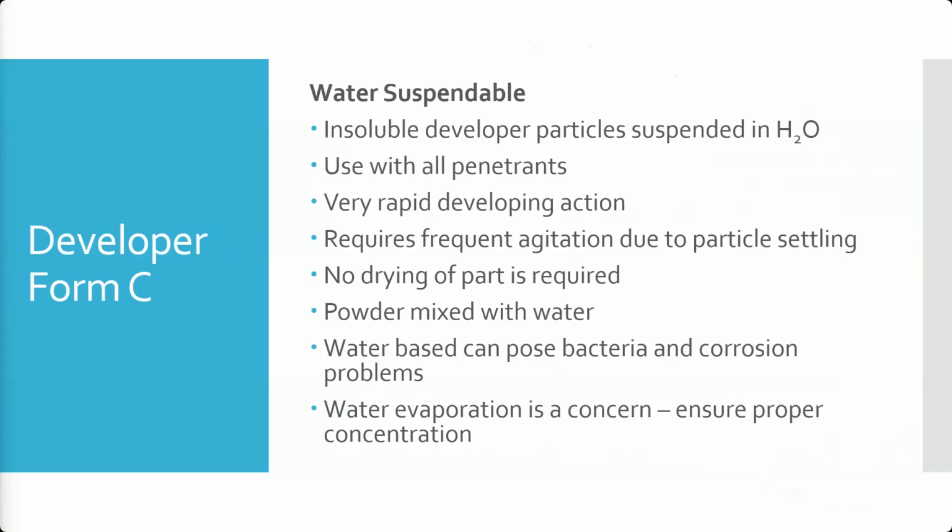Again, we don't have to dry the part before applying it. Again, this can't be used with water-based penetrants, with Method A penetrants. And again, it can cause those bacteria and corrosion things. Here also, water evaporation is a concern. If the water evaporates, that means the concentration goes up, and there's a minimum and a maximum concentration. It's kind of like taking the particle levels for magnetic particle, right? You need a certain amount, but you don't want too much.